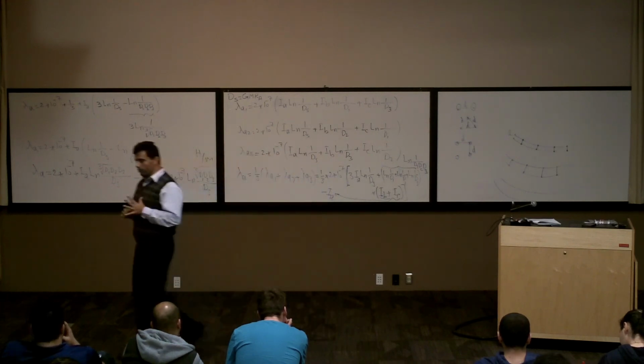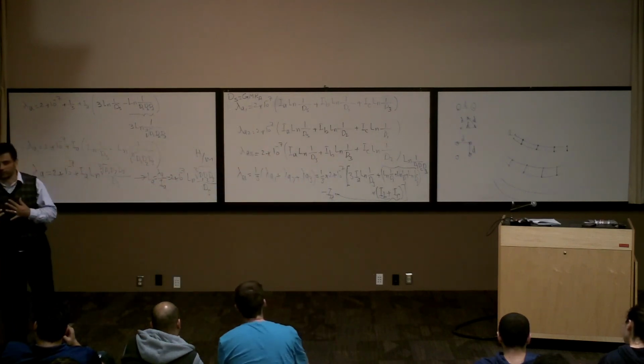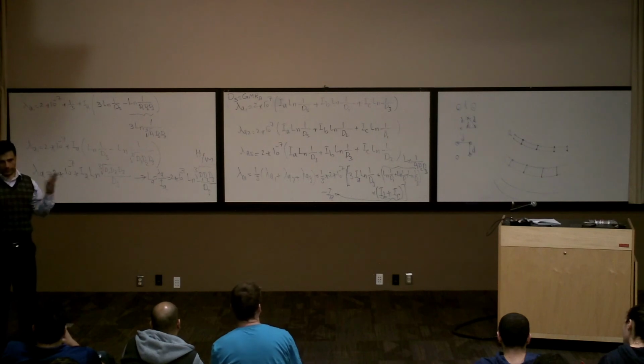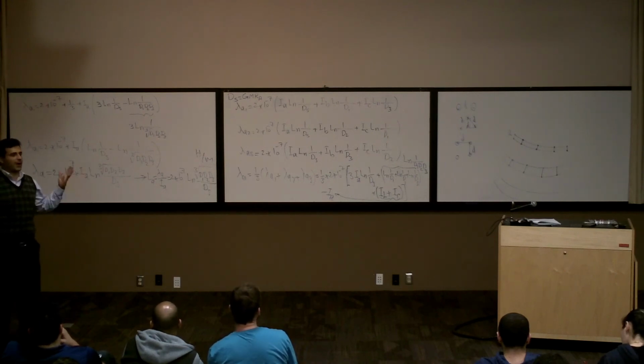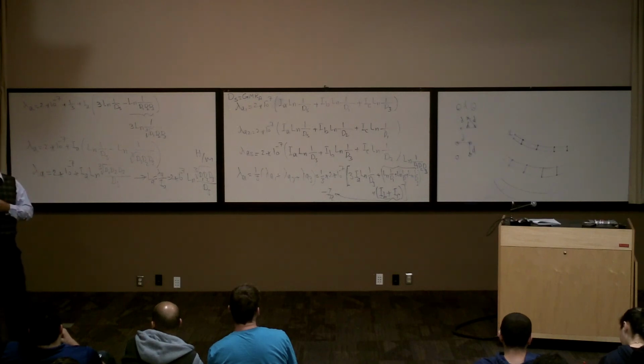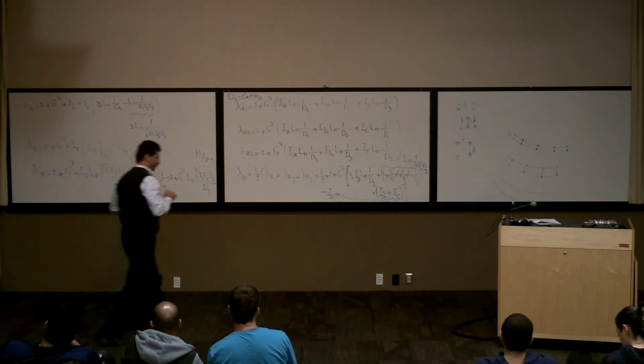So when we bundle them, what parameter is going to change in the inductance? We said in general, inductance is 2 times 10 to the power of minus 7 ln of GMD over GMR. Does this one change the GMD? No. Why? Let's do the real case.